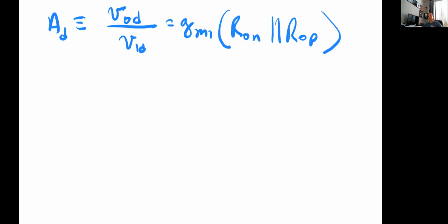So you don't get the degradation of the gain because of the output resistance of the dynamic load. And then the cascoding of the dynamic load is doing its part as well as an improvement. So that's basically what we looked at in chapter 8. And now we're just putting two of those legs of 4 transistors each as a differential pair. So this is for 1/2.